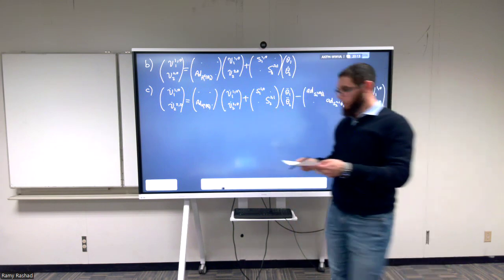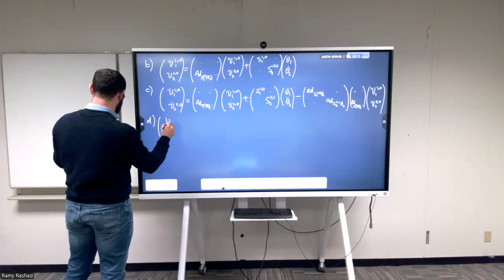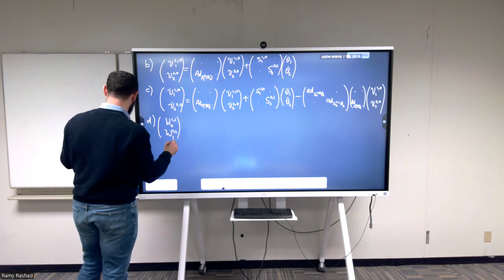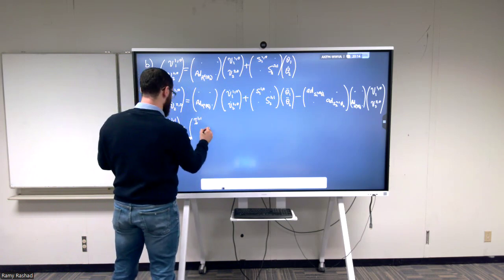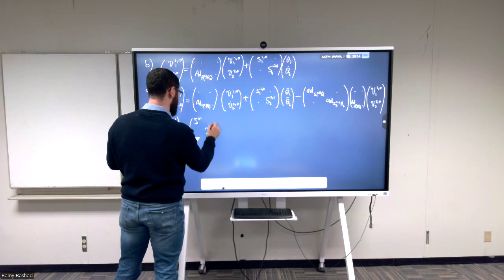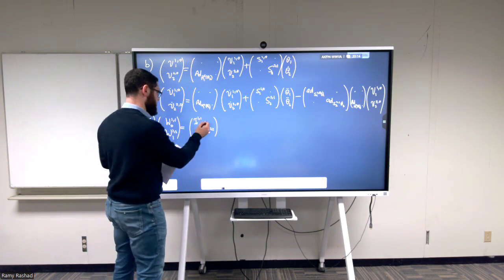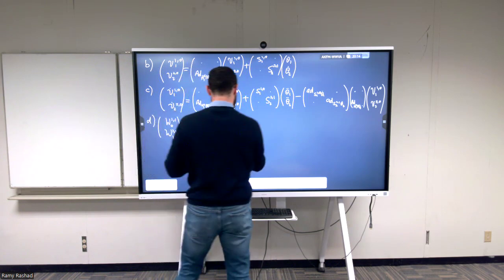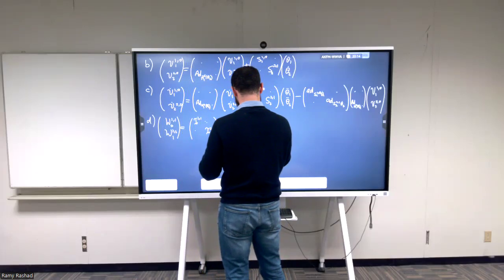Okay. Then we have in the D expressions, we had the wrenches, is equal to the inertias. We're going to combine them into a huge matrix. Remember, the inertia itself, each one of these was a 6x6 matrix. So we're going to combine them together. We have the V dots. We had the expression that was for the Coriolis terms and the gyroscopic terms.